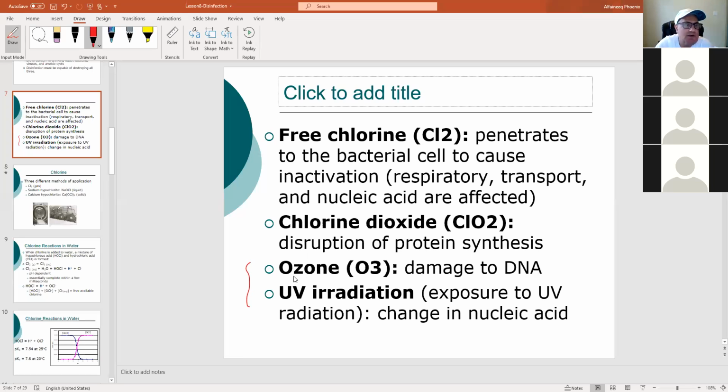Maybe you still remember from discussion last semester why chlorine is desirable. Because it lingers around, right? It leaves residual chlorine in the pipelines after treatment. This is how, when it reacts with different kinds of organic material inside the water itself, it leaves that residual. In other words, it's not enough when you finish with filtration.